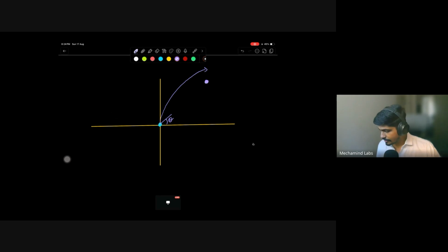It can happen. So this is being defined by the k angular, which we have put in the proportional controller. It is 6.0. It is not a fixed number. I have put that after doing many hit and trials, seeing what is working well. So that's not a number that is fixed. You have to put it accordingly. It will work for your turtlesim because your turtlesim and my turtlesim are the same, but it might differ for robots which we are building, depending on the motors.